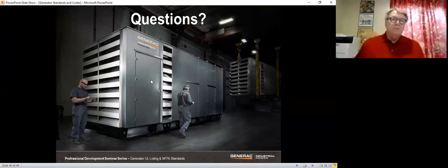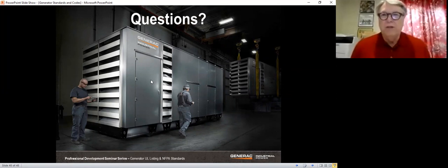And so that makes me a little bit hesitant to have emergency stop push buttons located in places where the public can have access to them. Even in an electrical room, it's just so easy to do that and not realize that you've done it. One of the good things is when you do push that emergency stop push button, you will get a warning on the generator controller, so you are going to get an alarm. So it's not quite as bad as I'm making it out to be. But a lot of people who have emergency generators don't install that push button for that reason. And I'm not telling you to do that because the code requires you to do that. But it's only required on an emergency generator.